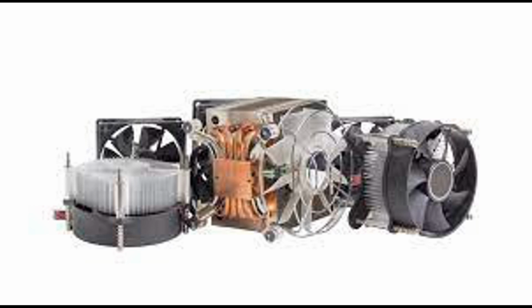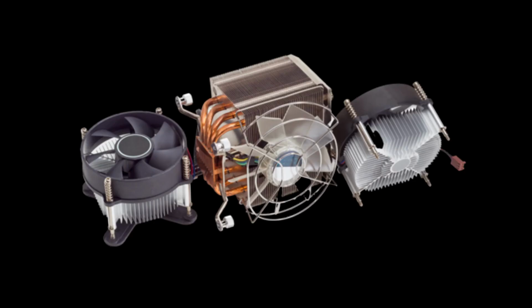Functionally, copper heat sinks serve the same purpose as other heat sinks, to transfer heat away from electronic components and dissipate it into the surrounding environment. However, copper's superior thermal conductivity compared to materials like aluminum allows for more efficient heat transfer and dissipation. Copper heat sinks typically feature a design optimized to maximize surface area, similar to aluminum heat sinks. This design may include fins, ridges, or other structures that increase the contact area with the air, promoting better airflow and heat dissipation. Additionally, copper's malleability allows for the creation of intricate heat sink designs tailored to specific cooling requirements.